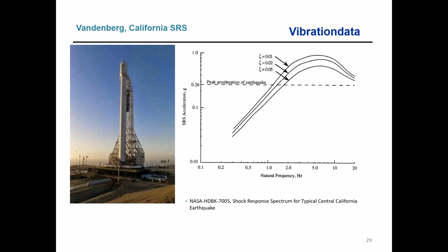And then that person said, yeah, but there's then the distance attenuation. So the distance attenuation over 35 to 40 miles could conceivably bring the peak ground acceleration down from, say, 0.35 g's to 0.26 g's. Well, that's my plausible rationale for what you're seeing here. Don't know for sure, but it sure makes a good story.